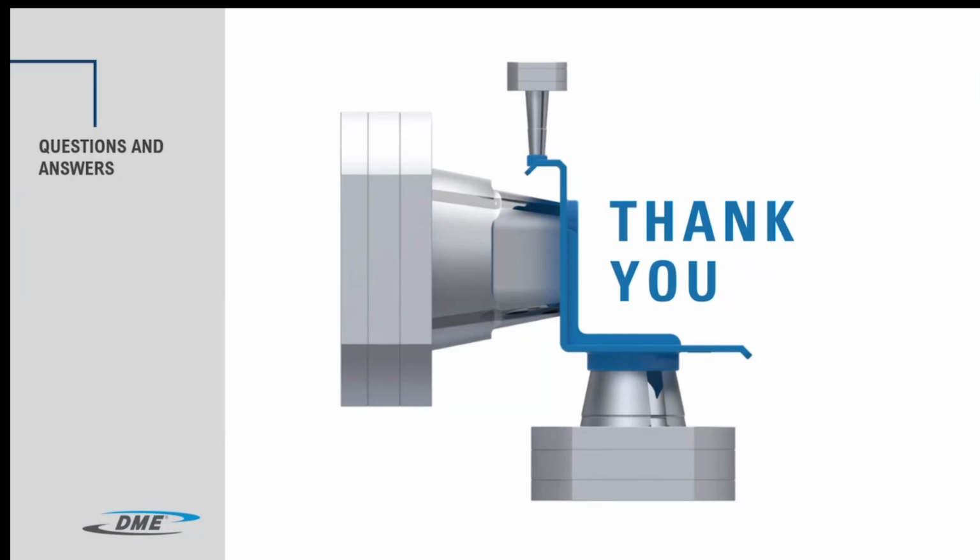Adam, in my previous session, I explained the working principle. Usually for an unscrewing device, there is a need for separate time to unscrew it back and for ejection. But in S-core, it can be a parallel application. While the mold is opening, the core will collapse, and while the mold is closing, it will come back to the original position. So you can easily calculate the time. I don't need any additional time for the unscrewing application.